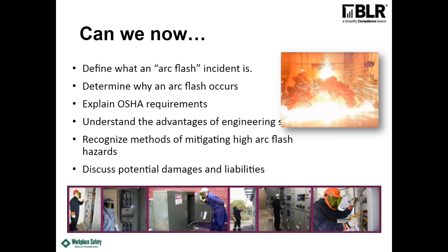All right, so we're going to come down and break down what we looked at today, and then we're going to take some time for some questions. So first off, we hopefully defined what an arc flash is. It's incident energy, and it's measured in calories per square centimeter. That's a measure of the heat and energy from this thing and pressure.